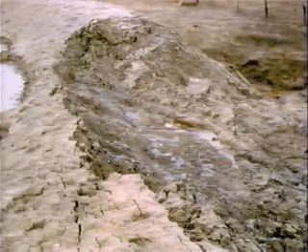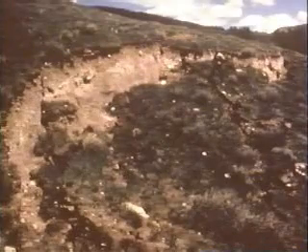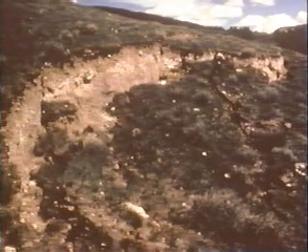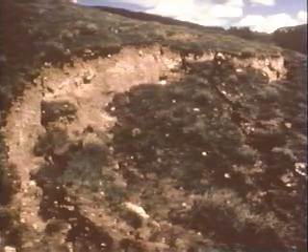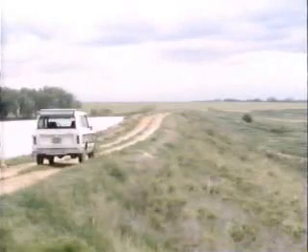Look for well-defined scarping produced by the movement of embankment material as seen here. Arc-shaped cracks in the slope show us that a slide is beginning. These cracks may develop into a large scarp in the slope at the top of the slide. Well-defined scarping in either the upstream or downstream slope indicates serious structural problems. When this happens, action has to be taken quickly. Get a qualified engineer to determine the cause of deep-seated slides.